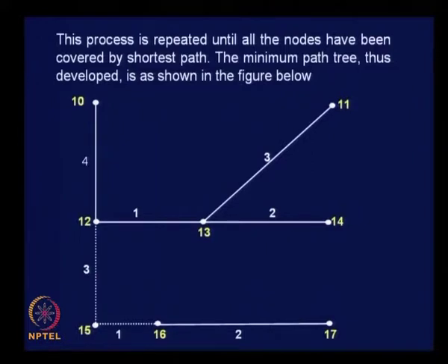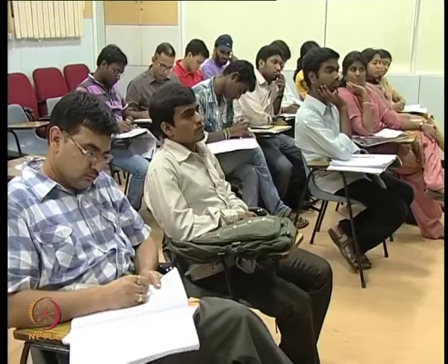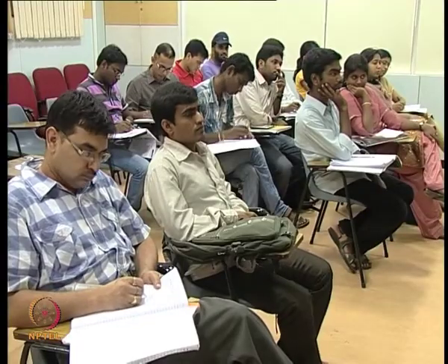This is what we are looking for. When you assign traffic, you can assign using this network. The rest of the links are useless as far as this particular zone centroid is concerned, if you take the minimum path tree as the basis for traffic assignment. So, extend this methodology to cover the whole of the network, clear?